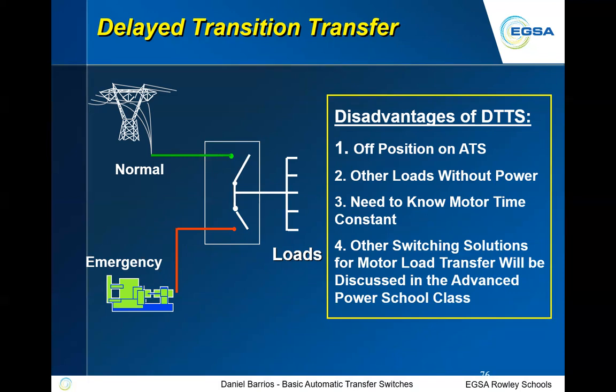Typically, because you have such a short period of time, you're dropping 1 second to start the generator. And you know, a 450, a 500, 600 kW generator can ramp up very quickly. A 2500, 3000 kW generator, that's a lot of inertia to move within 7 seconds or so. Why do I say 7 seconds? You have to get the start, it has to ramp up, it has to stabilize, and all of that has to happen, including the transfer switch transferring within 10 seconds.